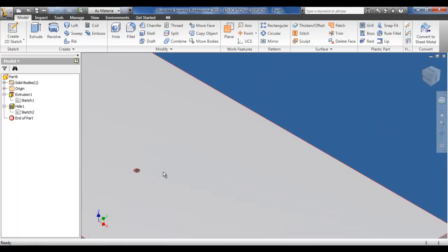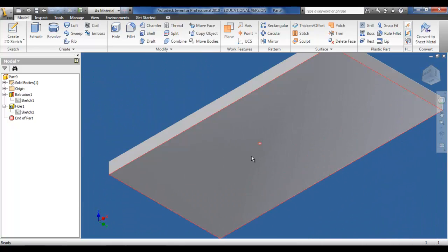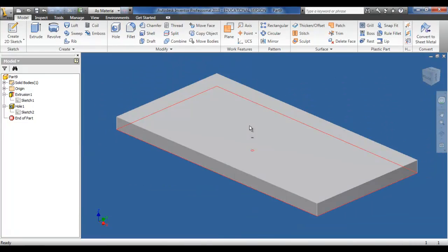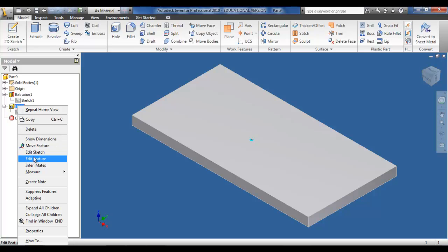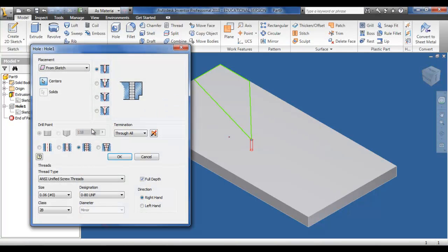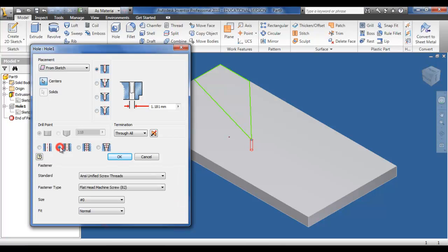And this is set up in the exact specifications that are required, that are set up in the dialog box. Now you can see as well, the hole is mounted at the bottom and the thread is full depth. Back into edit the features, I can now select other types if I require.